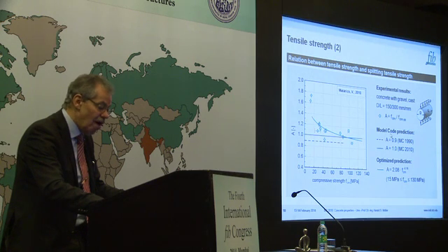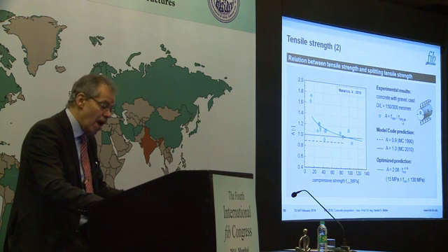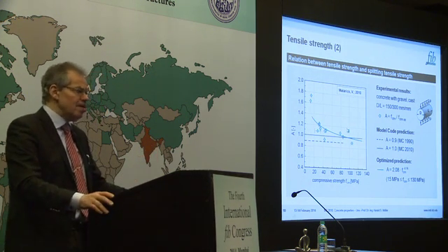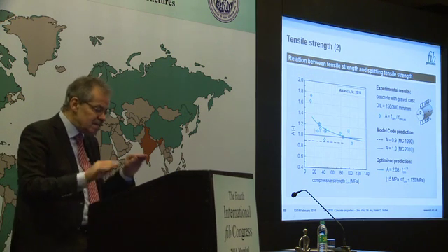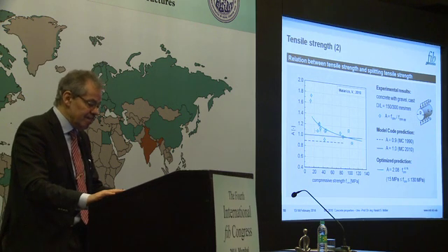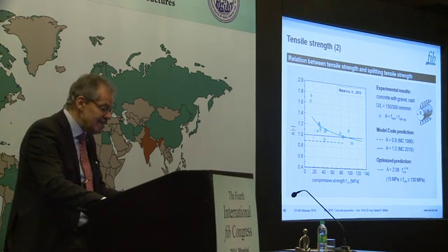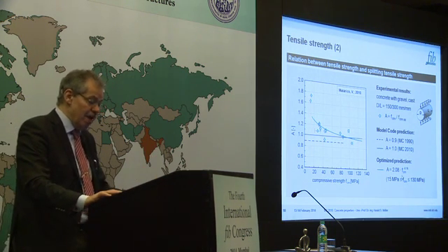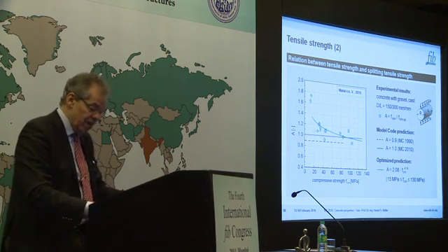A is the ratio of the tensile strength measured in a direct tensile test divided by the splitting tensile strength. But finally, the commission decided to stick to a fixed value. It is 1.0. But on the left-hand side, on the commentary side, in the new Model Code, you have this more precise, this optimized prediction equation, which you might apply if you feel it is necessary.